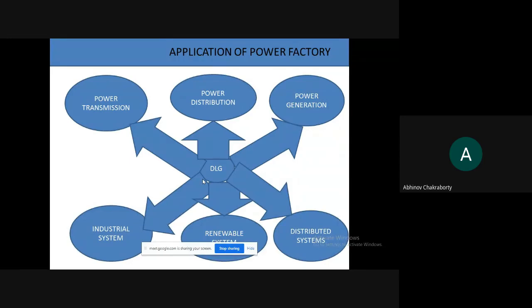And finally, we come to the distribution part, that is the power distribution part. Again, with the step-down transformers arranged over there, we will be having our isolators, we'll be having our circuit breakers installed over there. We'll mention the ratings of the circuit breakers, and accordingly, the functionality is going to take place, and we'll be having our GTD system arranged. But now, when I talk about distribution, we have two types of distributions, right? One is the primary distribution, and the other is the secondary distribution.